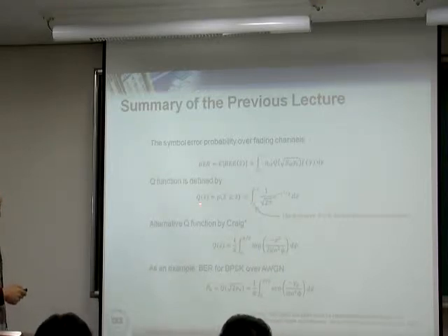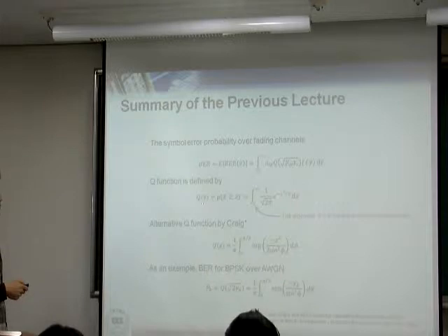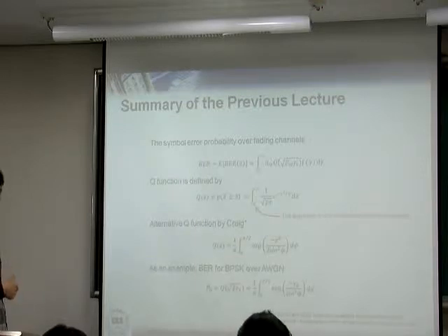And when we do the analysis, this Q function also needs to be inside of your integral equation. Now the Q function actually is an integration function. This one cannot be simplified further, so it is simply written as a Q function, right?